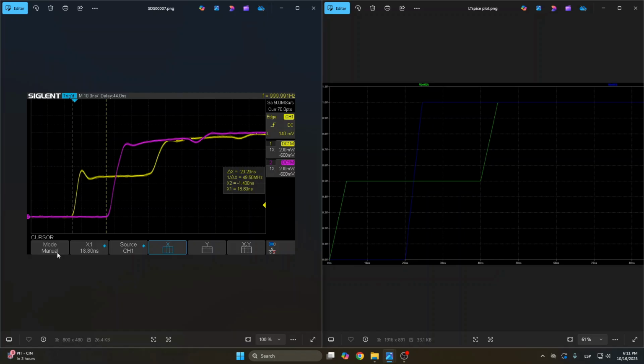So this confirms that our calculations about the propagation delay weren't that bad. They were fairly accurate. We can also determine that the characteristic impedance of the PCB trace is very accurate, because otherwise we wouldn't have obtained a value of 0.5 volts on this flat response of the yellow line. Remember that this voltage is the result of a voltage divider between the 50 ohm source impedance of the function generator and the 50 ohm characteristic impedance of the PCB transmission line.